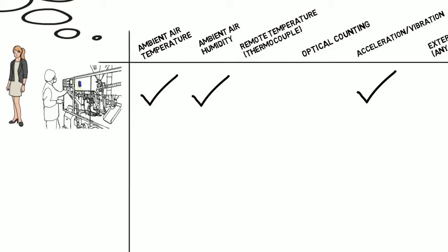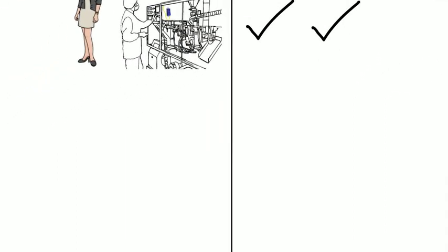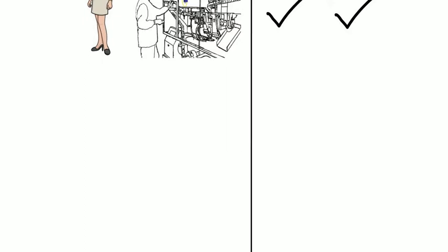These 3 measurements allow the team to learn how environmental factors affect their critical machines and the resulting quality of the product. They use that historical data to determine the limits of those environmental factors that would be expected to result in manufacturing problems. And they use the live MINX data to know, in the form of an alert, whenever those problem conditions present themselves, enabling them to take proactive intervention and avoid inferior output.